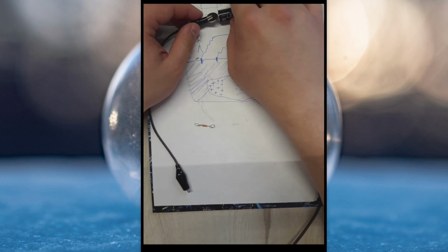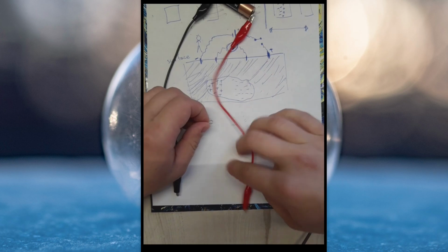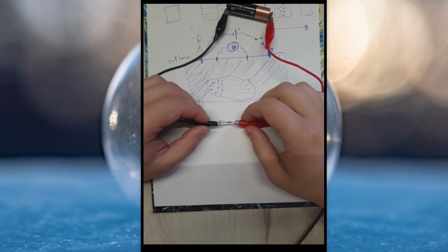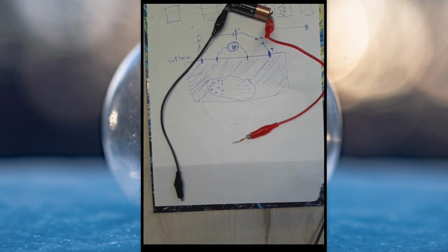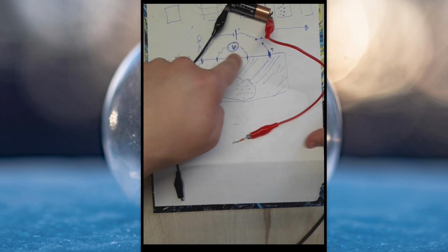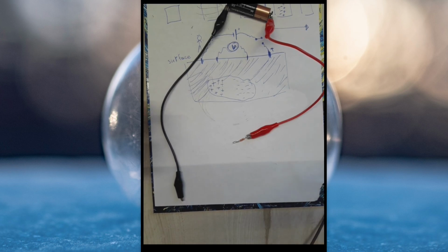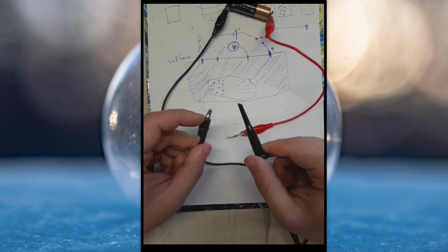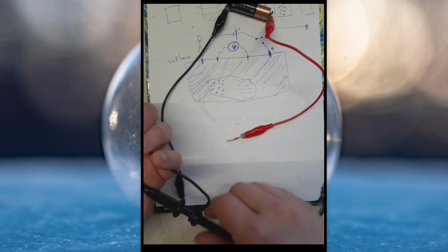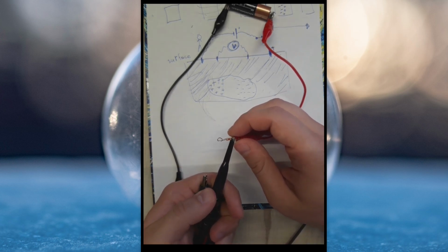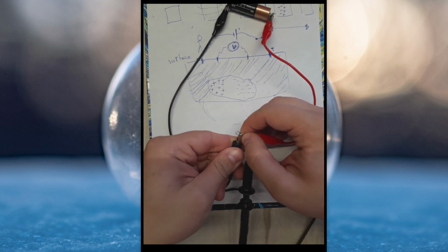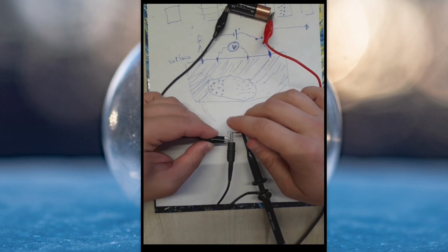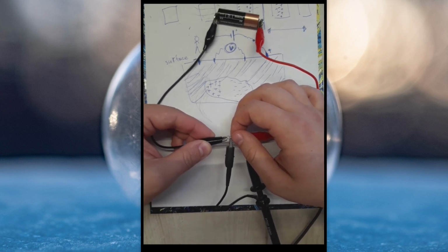We connect the battery to the sample, and of course nothing happens because we don't have our multimeter attached. I mean voltmeter. I'll use my oscilloscope for that. It will be much better to show the graphs. All right. I connect plus and ground to our resistor, our soil sample, I mean, and I connect my battery.